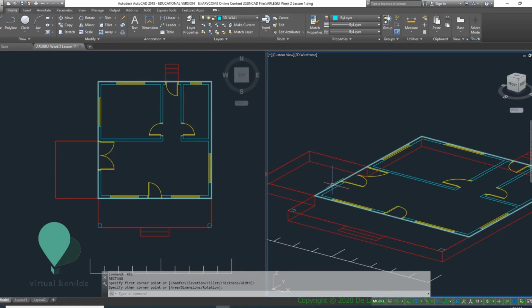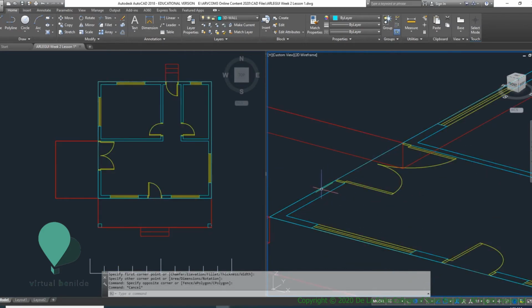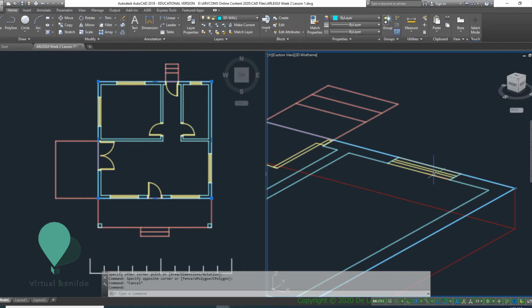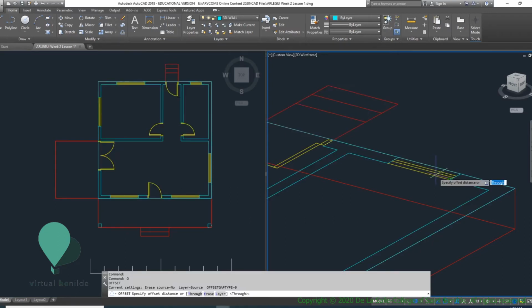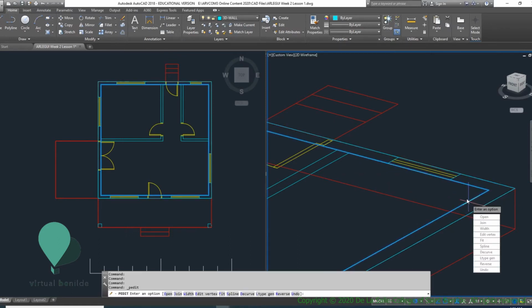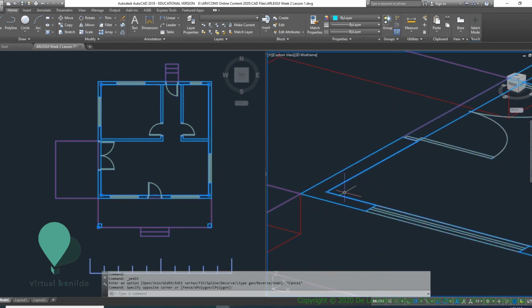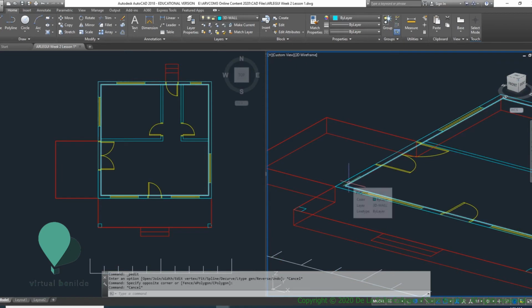Before extruding, of course, we need to create the inside of this, because I'm not just going to be doing a surface wall. So I'm going to offset this by 0.2. Seeing the value, since it's 0, type in 0.2 and go inside. There you go, just to check that there's another polygon inside. I'm going to extrude both of them for the meantime.